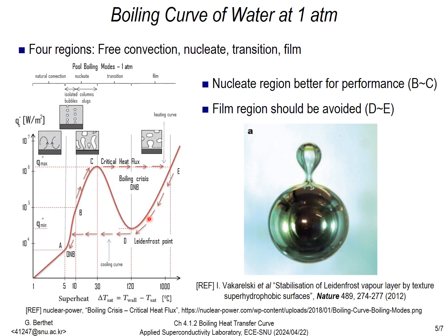This can be seen when a drop of water seems to hover over a hot pan, or in this case when a hot ball of metal is submerged in water. A film of gas is formed around the object, lowering the heat transfer. If we increase further the temperature difference, the heat transfer flux will eventually reach the maximum heat transfer of the nucleate region, but keep in mind that the graph is logarithmic, so this will happen at a very high difference.